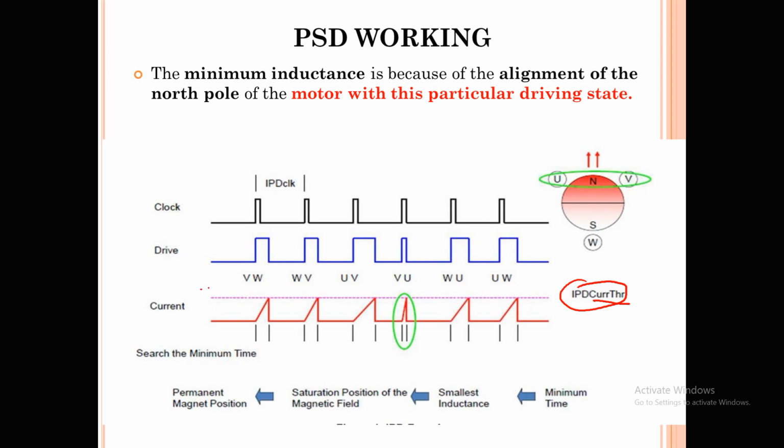If you select a higher value, it will go to this one and then come to this one, so the time duration also comes into the picture, and the graphs get changed. Sometimes it takes more time. If you select a higher value, there is a better chance to start your motor perfectly. At the same time, it will create some noise, and sometimes vibration and other things in the motor.